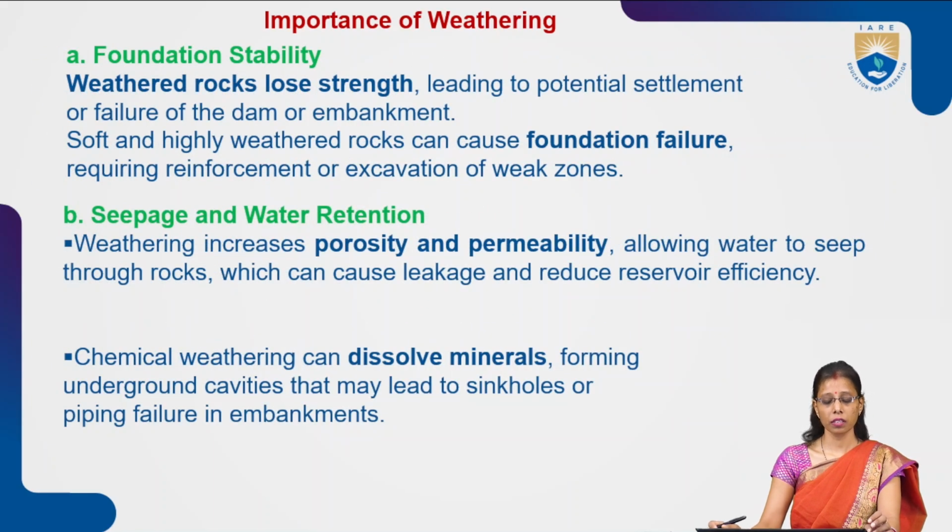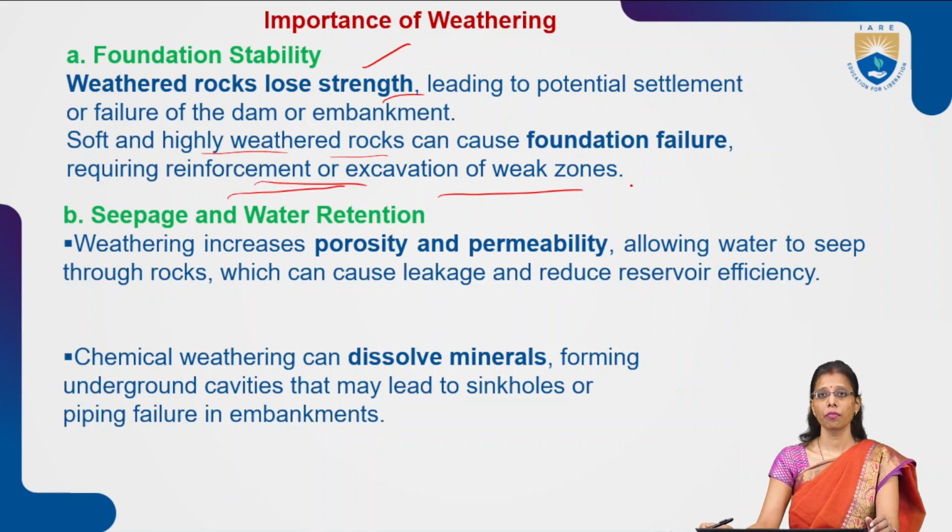Now, under this reservoir, the first thing we have to understand is foundation stability. What is foundation stability? Rocks lose strength, leading to potential settlement or failure of the dam or embankment. Soft, highly weathered rocks can cause foundation failures, requiring reinforcement or excavation of the weak zones. First of all, foundation is very important for a structure. Weathered rock has very little strength, which leads to potential settlement or failure of the dam and embankment.